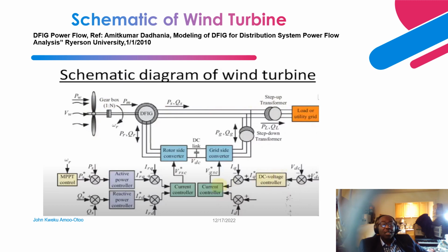Okay, so we have a step down transformer that steps the voltage down so that the lower voltage can be utilized by this back-to-back converter. I think the voltage is typically about 690 volts, right? Or you can have a three-winding transformer, where the third winding, at a much lower voltage of 690 volts, can be utilized by this back-to-back converter, instead of having a separate step-down transformer for it, right?